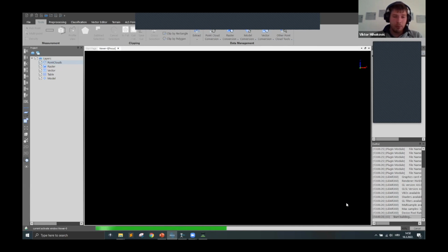After we import the data, we will take a look at the alignment of our strips, or of our passes in 2 different directions. If needed, we can then improve the accuracy of our point cloud, but that depends on whether you have good calibration. Most of the time, if you have good calibration, there is no need to be stressed about this. So now we are at 85%. The point cloud will be imported quite fast, and then we can proceed to strip alignment.